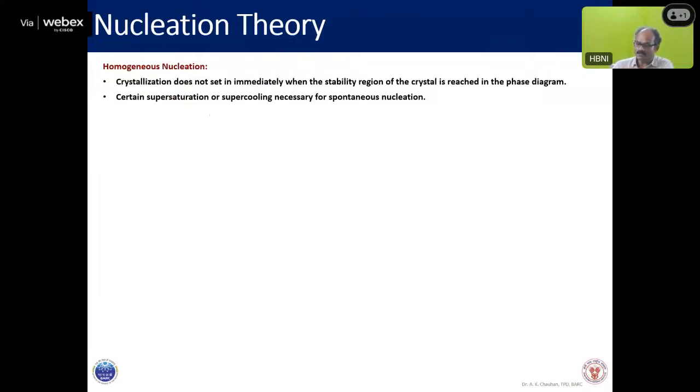It needs certain nucleation in order to start the growth. So for this, the first thing you need is a certain amount of supercooling. Supercooling means the temperature difference, or the temperature which has been below the melting point. So if I brought it from 1000 degrees to 990, in that case, I can say there is a 10 degree centigrade supercooling.